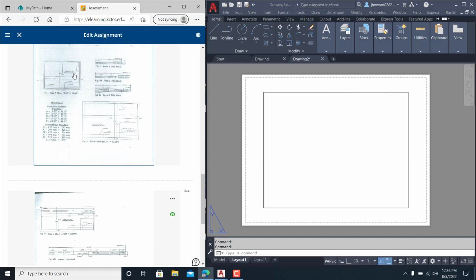It's hard to see that. But we're going to make a title block going around this thing, and it tells you specifics, but I would recommend a 1/2 inch border on this A size paper, because sometimes when you go to the requirement like 3/8, sometimes it doesn't plot right. It'll plot and not have all your title block on there. It just doesn't look good. So we're just going to stick with a 1/2 inch offset around the outside edges, the perimeter of your paper.